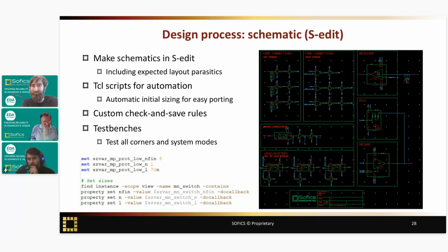So next question, which is related, is from Stefan in Germany. I think you started to touch on this, Wouter, but how much supply current is usually used for the VM voltage generation? Yeah, I think if we use an LDO type design as a bias generator, we typically aim at a maximum of 60 to 100 microamps of steady state current per bias generator, which you can typically share over multiple I/Os.